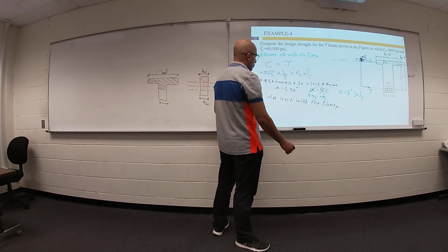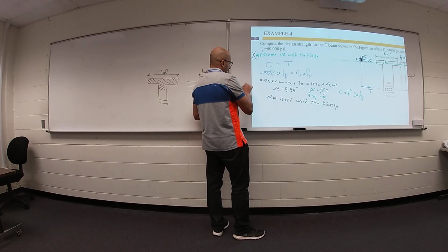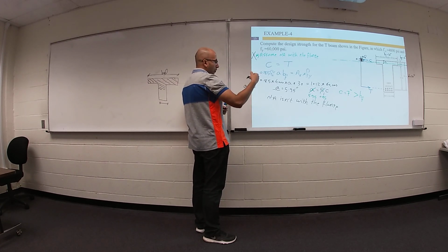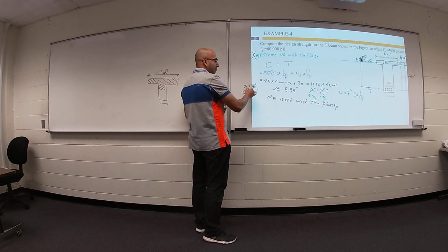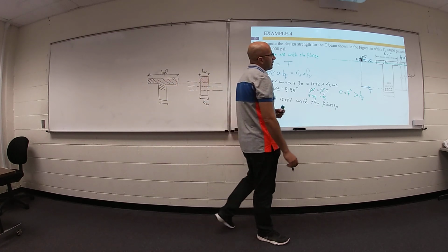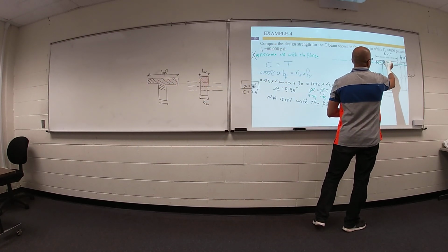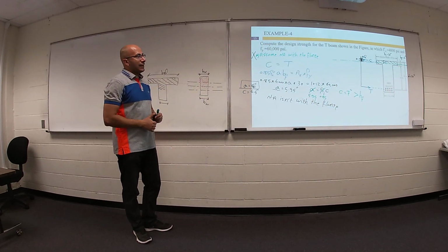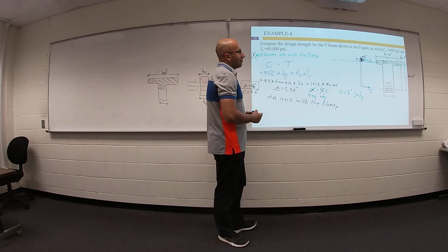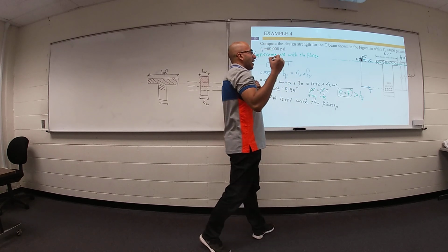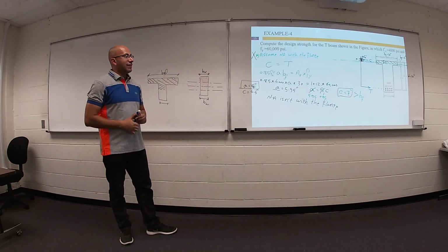But if your a equals maybe 3 or maybe 4 inch, your c will be 4.5, for example. So I think you still can say I can use this flange and my calculation will be correct. Okay? So your neutral axis is outside the compression flange.